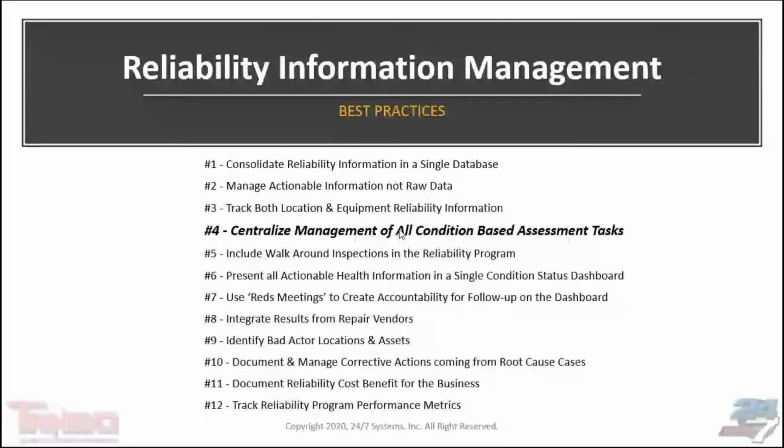Best practice number two was clearly indicating that you want to deal in what we call actionable information, not the raw data. The organization that we're working with as reliability professionals, the maintenance department, the operations department, they don't understand the squiggly lines in a vibration FFT, or may not understand the radiometric images and all the nuances of infrared thermography. They want to know what the analysts that are using those technologies see in that information. They want to know their findings and recommendations, and that's what we mean by dealing as a best practice in actionable information, not just the raw data.